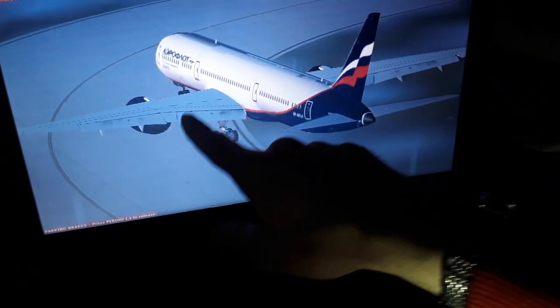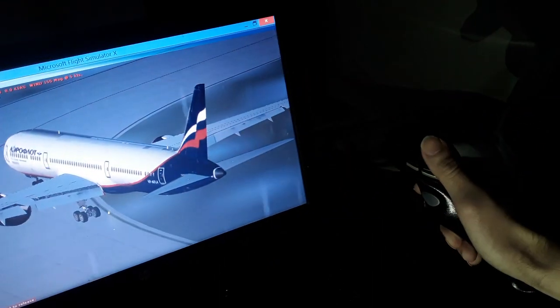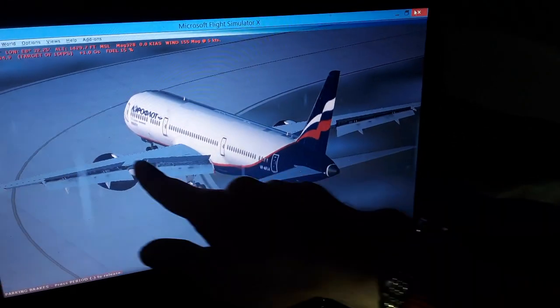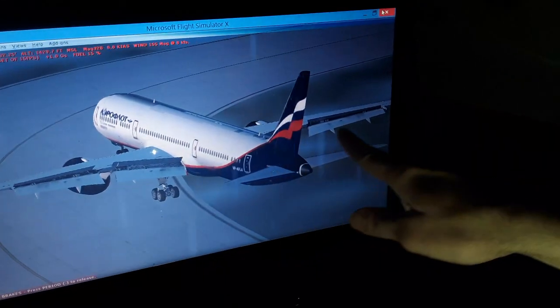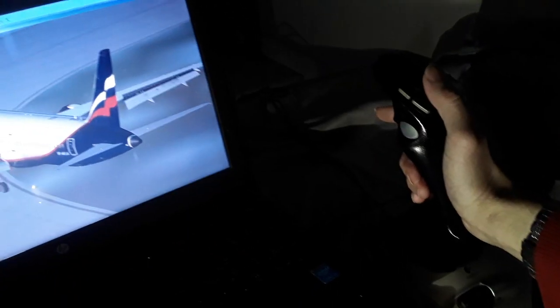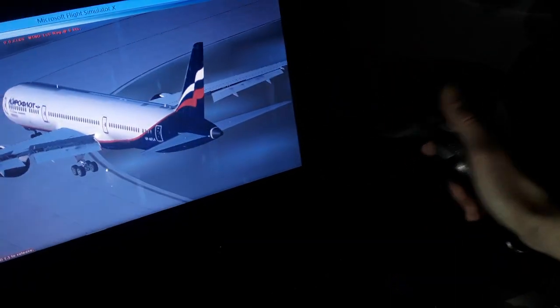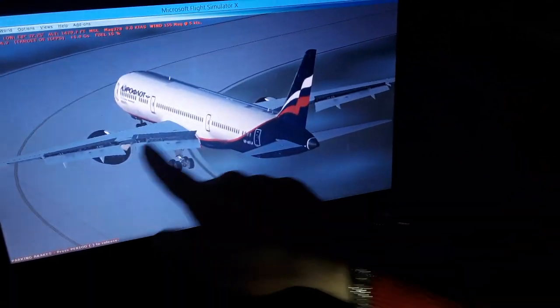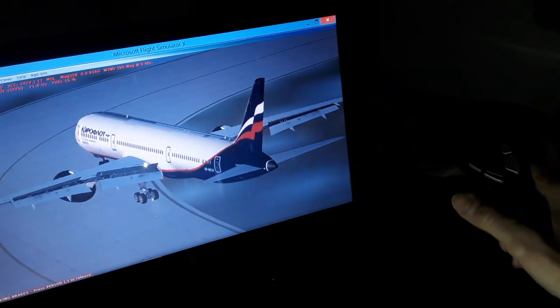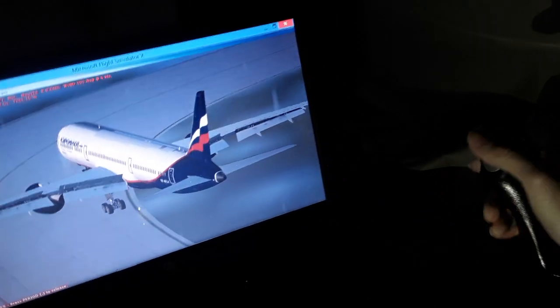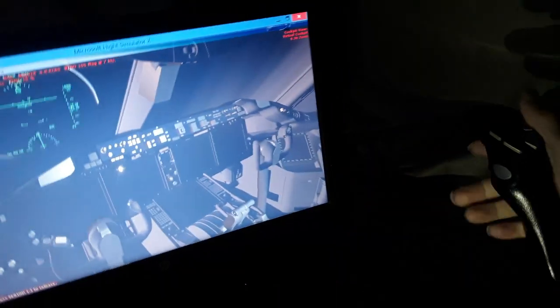Also we have one more flight control. We have the flaps in the Boeing. So you can see now the spoilers extended for speed brakes over here, and the flaps also are fully extended, as you can see in the slots. So we have one more for controlling the ailerons and the spoilers. You can see the aerodynamic lift difference between the left and the right wing when flying. It will make the aircraft roll in either the left or the right direction.